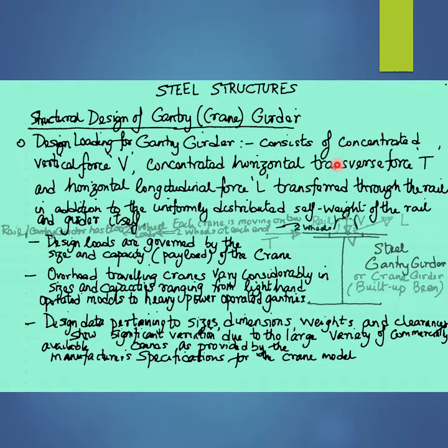Hence, the concentrated vertical force V due to the weight of the crane and the loaded trolley of the crane or the loaded crab of the crane, including the payload of the crane, and the concentrated dynamic horizontal transverse force T acting in the transverse X direction